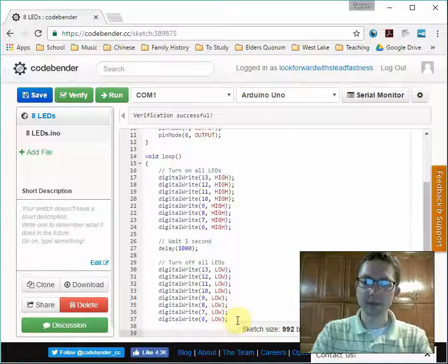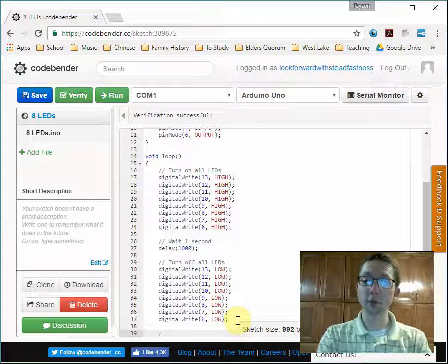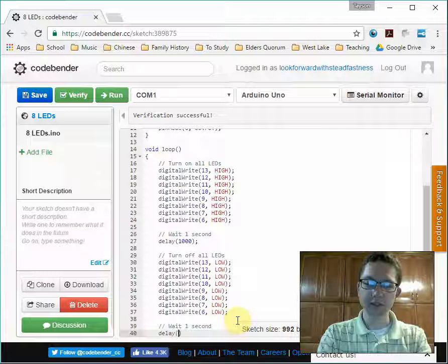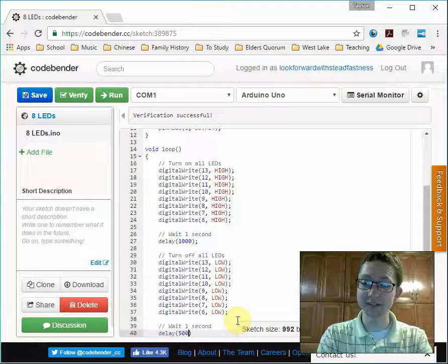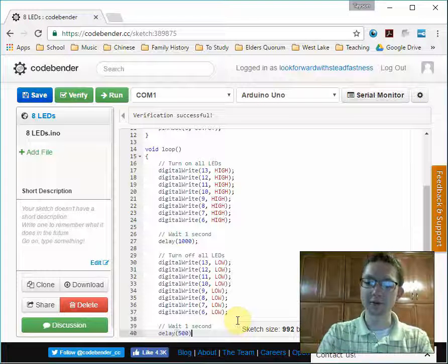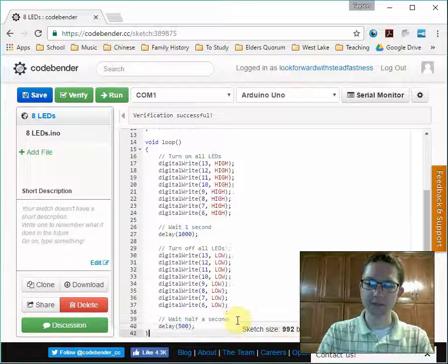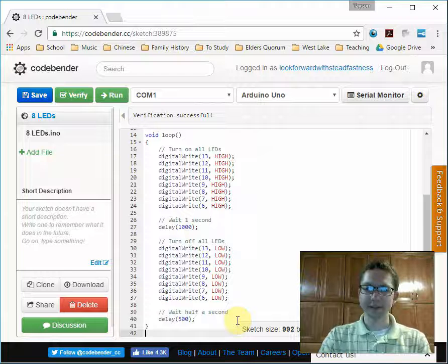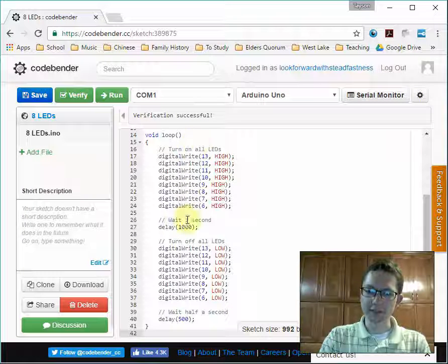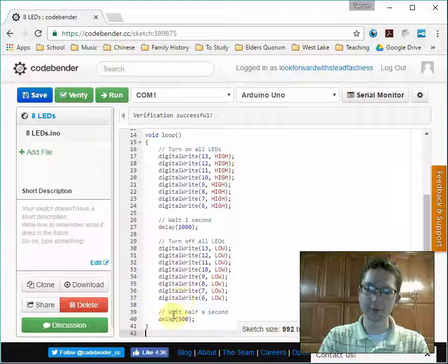Okay, great. And now we need to do one more thing. We need to put in one more delay. Wait 1 second. So we'll put in a delay, and let's have it wait for only half a second. So we'll put in a delay of 500 milliseconds, or half a second. Wait half a second. Okay. So here's our loop. It's going to turn all the LEDs on, wait a second, turn them all off, wait half a second, then come back up here, turn them on, wait, turn them off, wait.